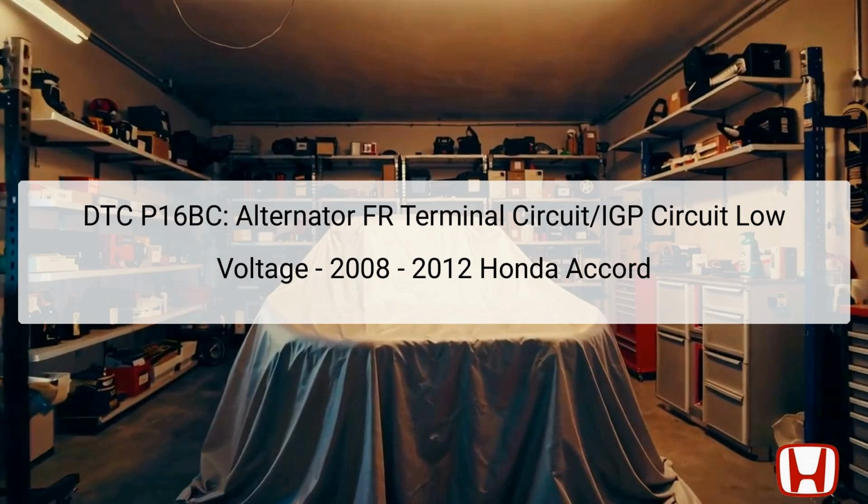The alternator's FR terminal is connected to the voltage regulator, which controls the alternator's output to maintain the battery charge. Understanding this DTC is essential for diagnosing potential issues with the vehicle's charging system, which can lead to electrical failures if not addressed promptly. In this presentation, we will cover the steps necessary for efficient troubleshooting and resolution of this